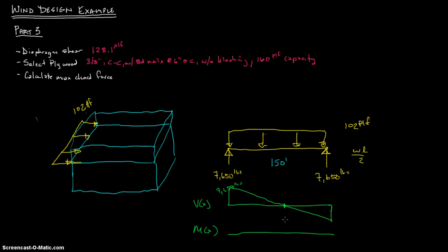So we know that slope will be equal to 0 right there, and then it'll slowly decrease more. So you got 0, slope is 0, and it gets heavier. It starts off high and then becomes low, and that's what your moment diagram will typically look like for a uniform distributed load. All right, and we can figure out what this number is right here.